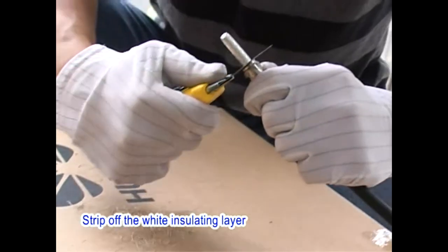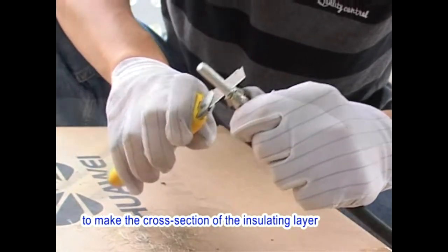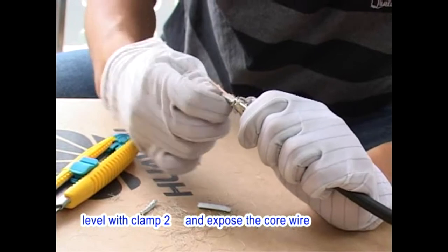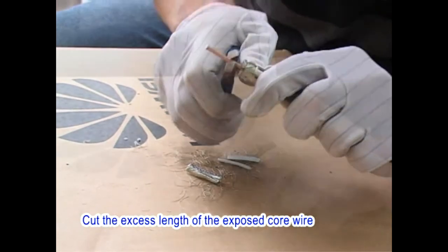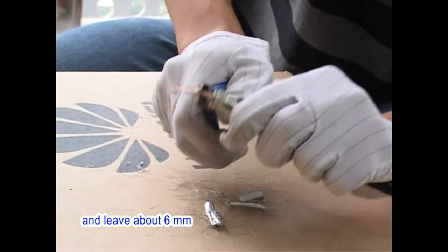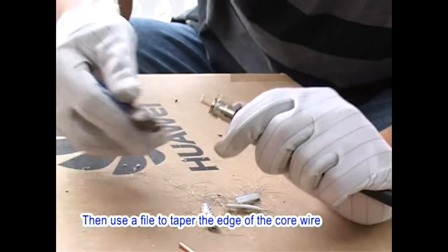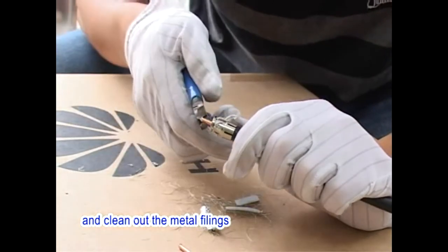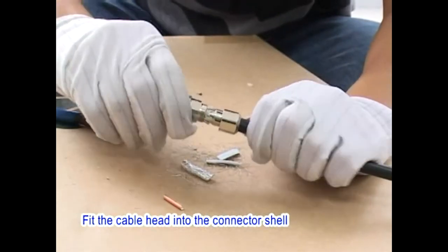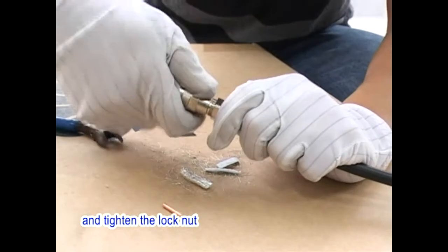Strip off the wide insulating layer to make the cross-section of the insulating layer level with clamp 2 and expose the core wire. Cut the excess length of the exposed core wire and leave about 6 mm. Then use a file to taper the edge of the core wire and clean out the metal filings. Fit the cable head into the connector shell and tighten the lock nut.